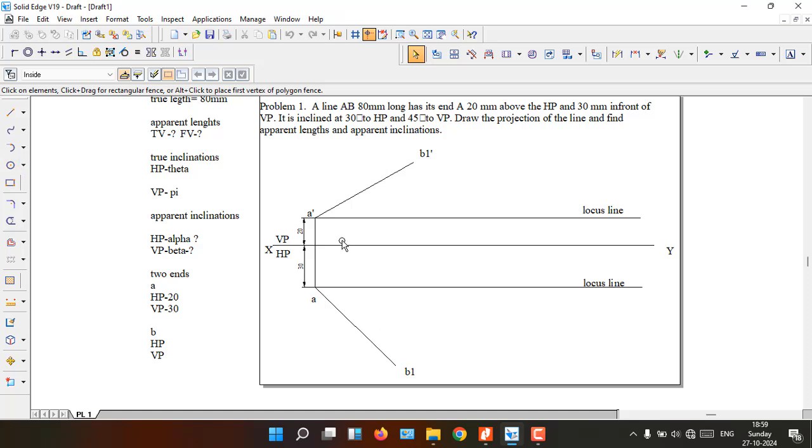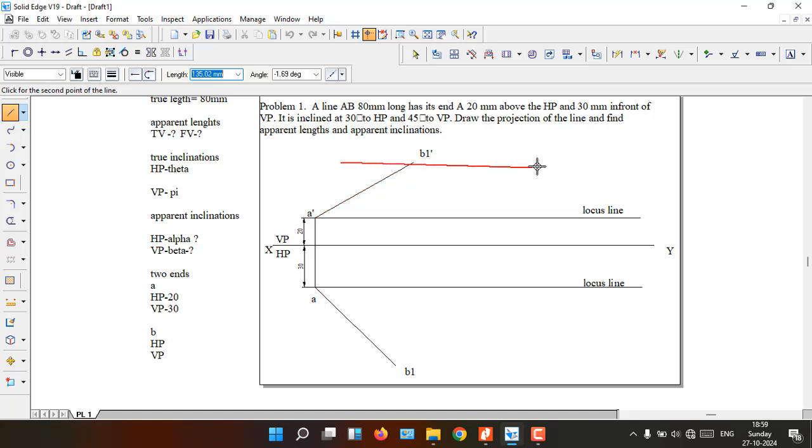Okay, now once you get one more end properly, what you can do here is draw one more horizontal line. Horizontal from the B, you can just see when you move from the B dash, there is a dotted line which will be appearing. Just click and drag. The same thing for B1, move to the left side, we need a reference, just drop one horizontal line.